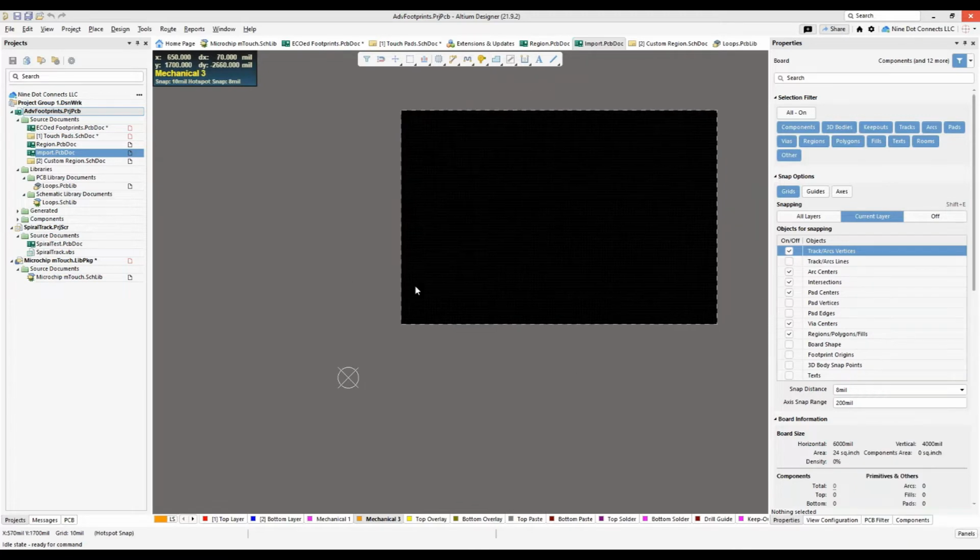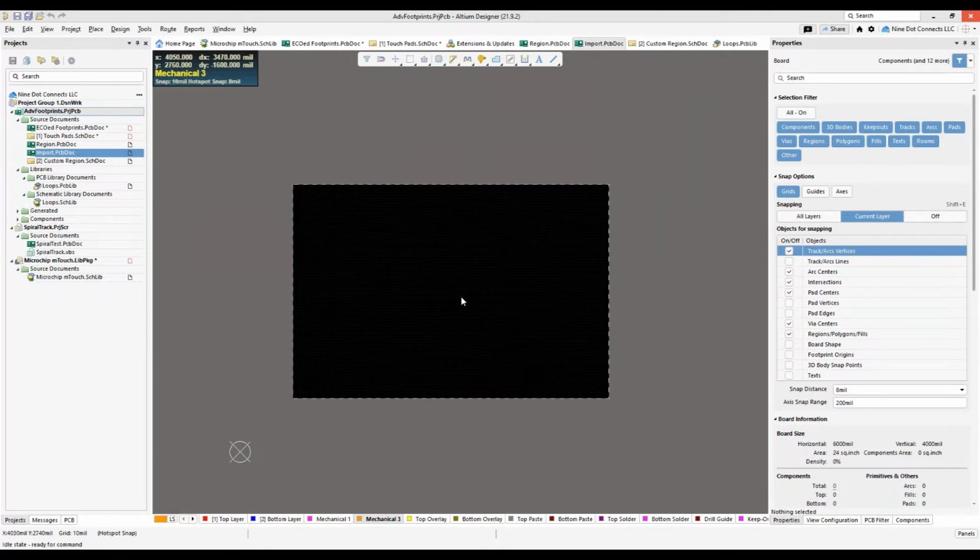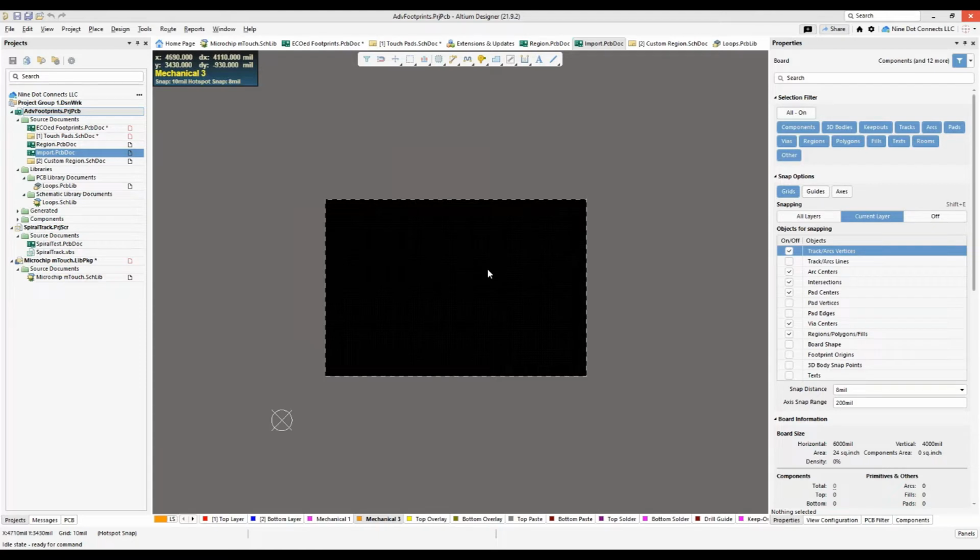But the fact is that we work in quadrant 1. And the reason I mention that is that a lot of people work in quadrant 1 and then they save it off. So when it comes in from that file, where's their point of reference? Their point of reference is off to the bottom left corner, not where they're working. And so that's just something to keep in mind, that when we try to bring something in, it's going to be a real potluck as to what they consider to be the 0 point. Okay? Especially with mechanical engineers, unless they totally understand that.